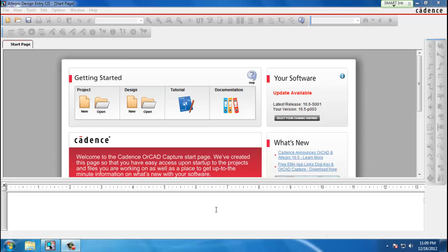In this video, we will go through the step-by-step process of creating a project and running a Monte Carlo analysis in PSpice. During a Monte Carlo analysis, PSpice performs several simulations, each time varying component values randomly within a specified tolerance range. At the end of the simulation, we'll be able to analyze how the tolerance of a specific component affects our desired output. So first we will start off by creating a new project.